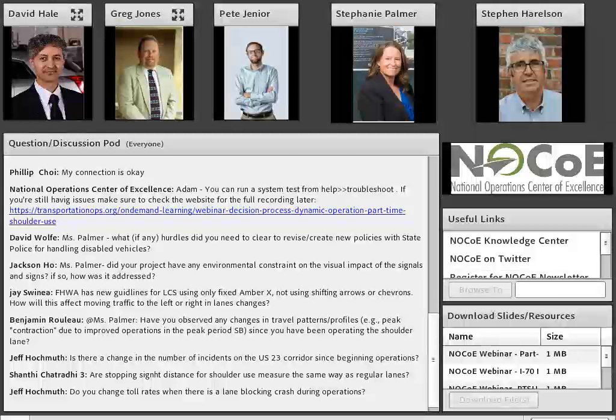Okay, and I think the second question also for Pete, is there going to be any guidance on where to best locate the sensors, such as either right at the physical gore or a third of a mile upstream of a physical gore? Generally, you want to have them right at a bottleneck. So if the physical gore, I'm assuming that's referring to like an on-ramp, in which case the on-ramp and the traffic from it causes the bottleneck, you'd want to have it right there, kind of right at that physical gore where the traffic streams start to meet. And we'll touch on that in the report.